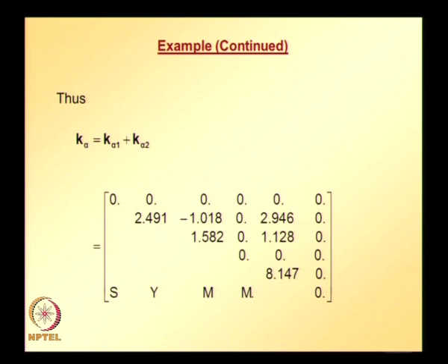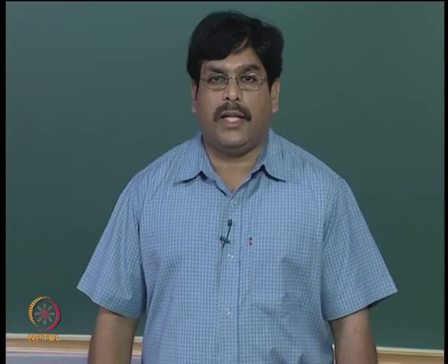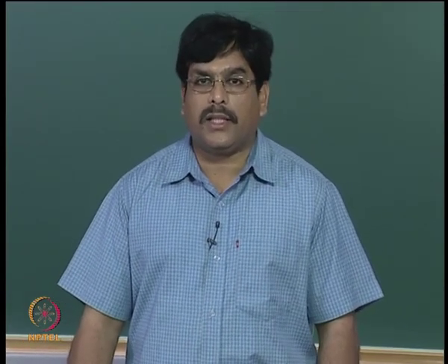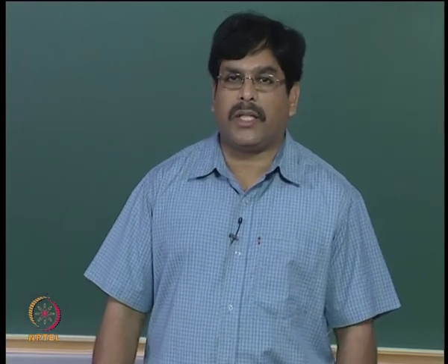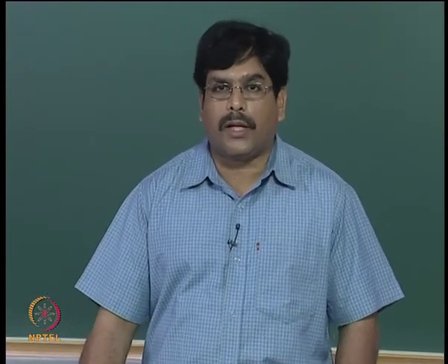So, this is the way we can evaluate these integrals using one dimensional integration along the boundaries of a triangular element, all the line integrals or boundary integrals. Given any problem, once we have the area integrals and boundary integrals, we can write complete element equations, assemble the global equation system, apply the essential boundary conditions and solve for the nodal unknowns.